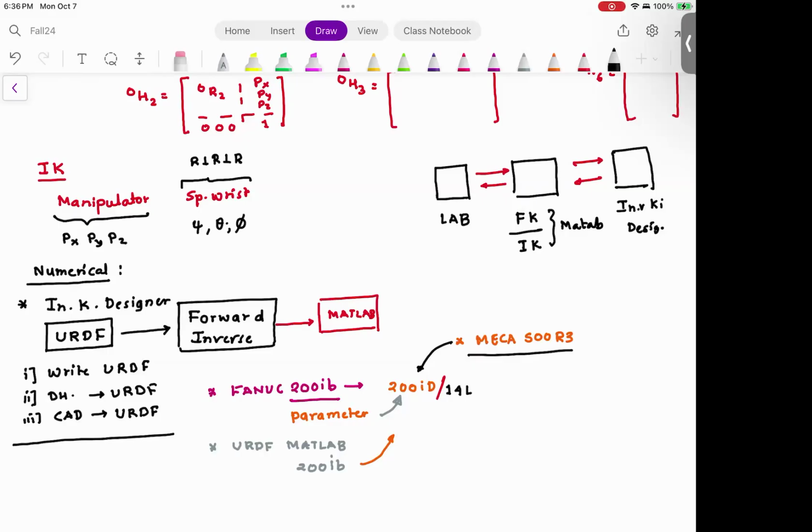The inverse kinematic solver can find multiple solutions, but the designer will see which of those is a possible solution, and it will give you that. So if you use your own inverse kinematics solver, the next step is to look at the joint limits and see which joint angles are possible. So that is the next natural step.